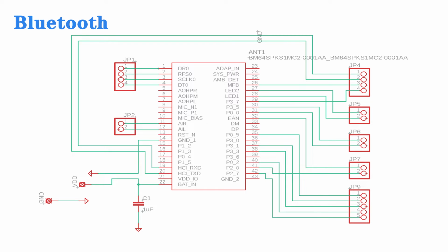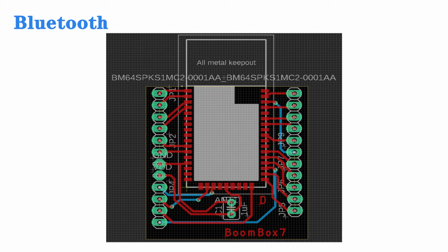For the BM64 module, we have decided to group the pins by functionality. This is why all these I2S, UART, LED, power, AUX, volume and sound control, configuration control, and system configuration have been grouped together by the categories. On top of that, we have decided to leave pins open that will allow for further improvements. This is why we have left the AUX pins and the volume and sound control pins as well. These features will possibly be implemented later on.